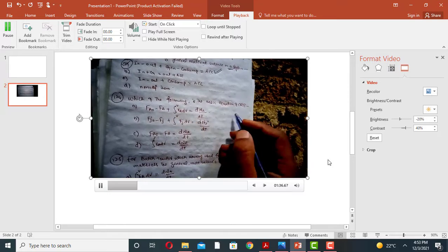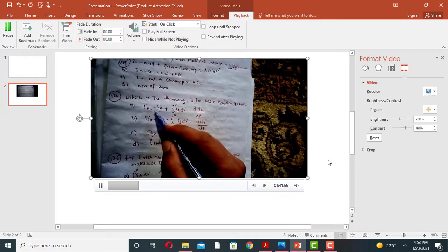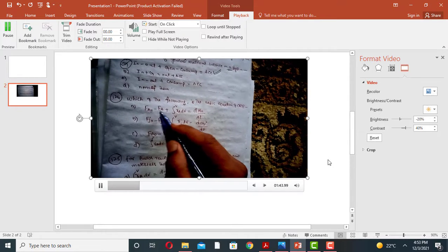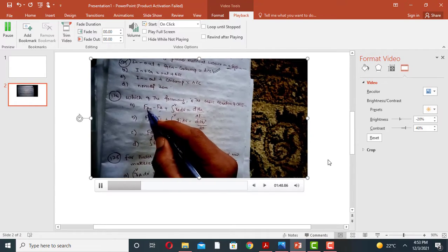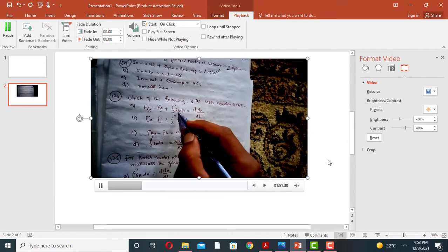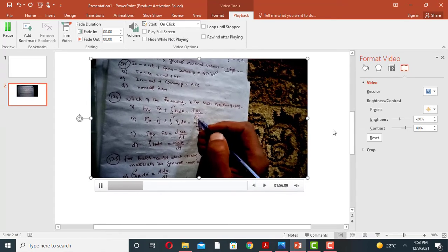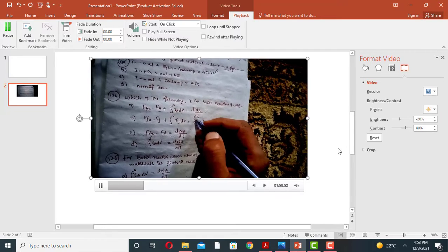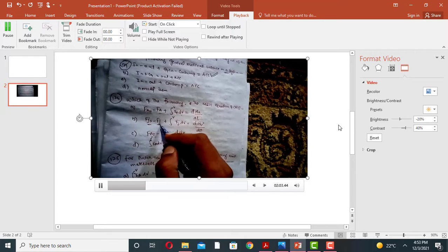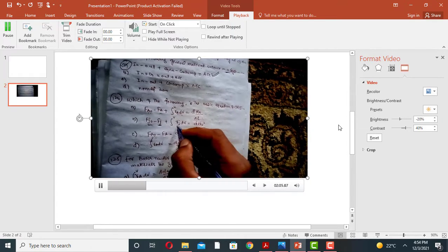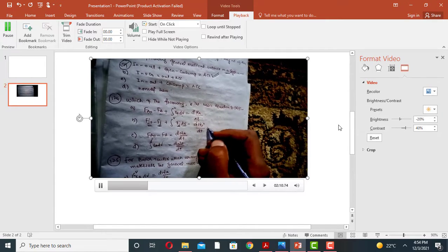Which of the following is the basic equation of chemical reaction engineering? FA0 minus FA, where FA0 is the molar flow rate of component A at the initial time and FA is the molar flow rate of component A at any other time, plus the integral of rA dV, where rA is the rate of A and dV is the change in volume, equals dNA by dt, the change in moles of A per unit change in time. The same applies to component J: FJ0 is the molar flow rate of component J, FJ at any time, rJ is the rate of component J, dV is the change in volume, and dNJ by dt is the change in moles with the passage of time.